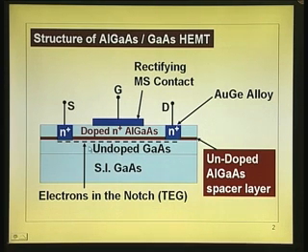We do not want them anywhere near these impurity atoms. So, put a spacer layer which spatially separates the donors. Spacer layer separates the donors physically from these electrons. Absolutely no contact, no Coulombic force of attraction, no scattering because of that. So, that is where it is put.